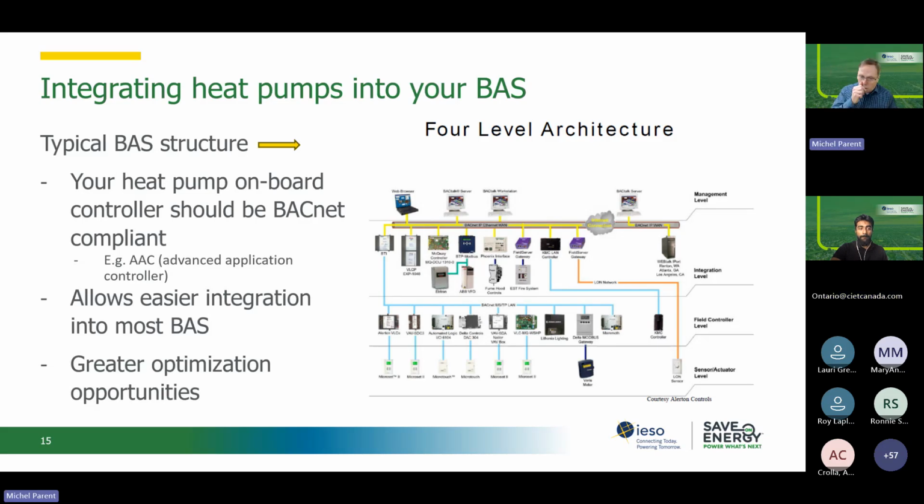No, it's not. A cascading heat pump system is really when you have an evaporator, a condenser, and then another evaporator that's using that condenser as its source, and it's going to boost it up to a higher temperature. If you only have one set of coils, one condenser and one evaporator, that's a straight heat pump. Cascade definitely means you will have two sets of those, and those machines actually feed one another to boost the temperature higher. As soon as you've got a cascade system, keep in mind that the overall COP will degrade.